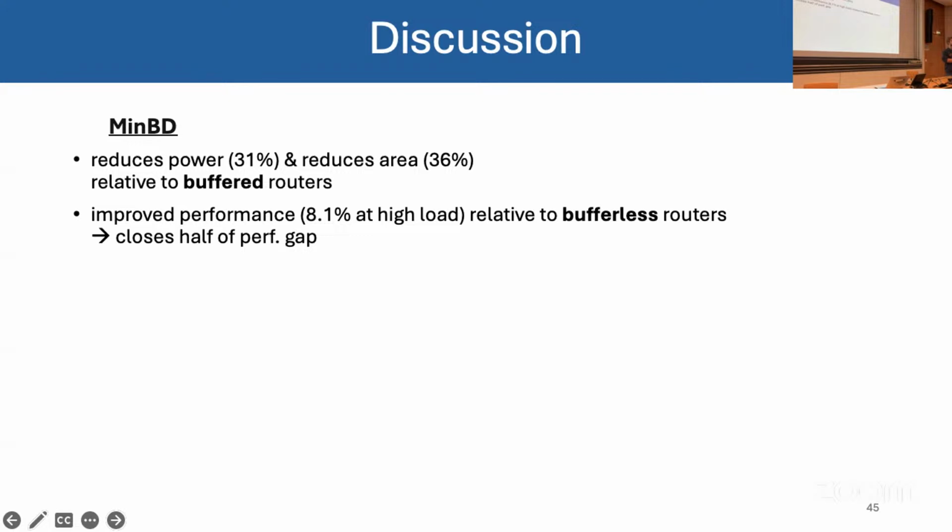And then we keep that information in the router in a table. Since other flits, like the body flits and tail, are also following the same channel, they are entering that router with the same link. And we use the metadata that we store for that link, such that they know which channel they need to go out. So that's the way we keep information. We don't store anything in the body, essentially.